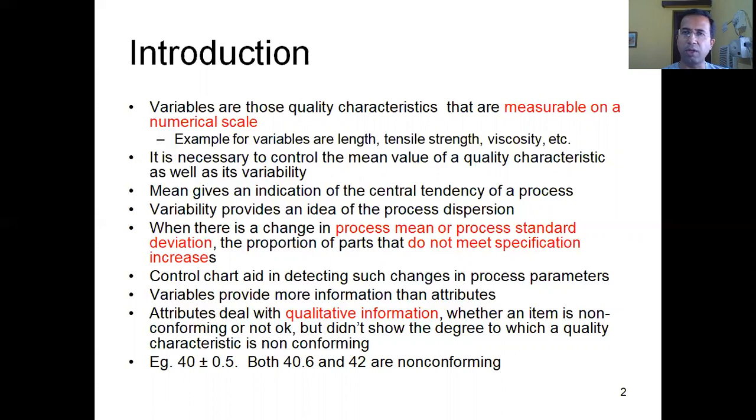That's why you name it a common cause of variation, which definitely is going to be there in all the output. The other cause of variation is a special cause of variation, where this variation is not present in every unit of the output, but it may be present in some units and maybe not later on. So with control charts, we want to remove special causes of variation. If you remove the special causes of variation, the only thing you will be left with is the common causes of variation, and hence predictable.